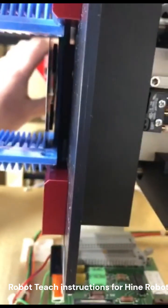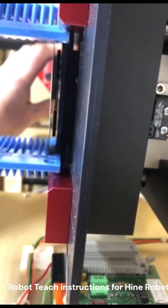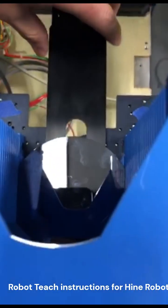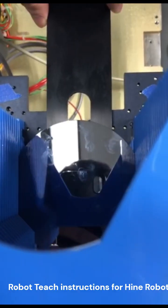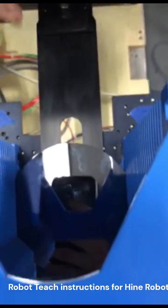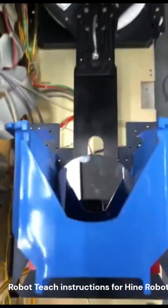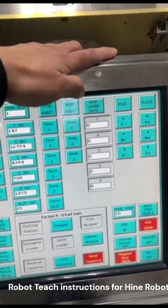As you can see, the arm is now directly below the wafer. Make sure that the arm is centered and that the holes will be in the middle of the wafer. When you have found the correct position, go back to your screen and hit Save Learn Data.